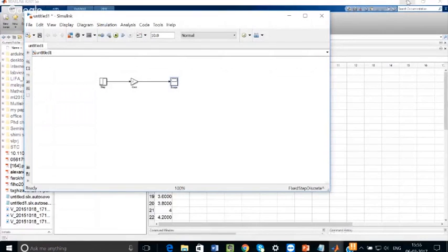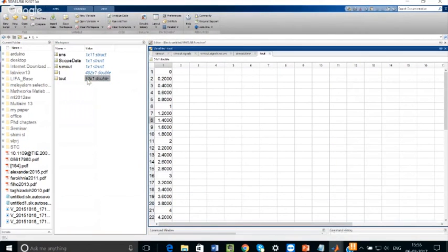So whenever you run a real-time system, when you connect hardware, you can never give it a variable step. You have to give it a fixed step. So here you can see the value, say 51. Now it has become 51. Earlier it was repeated, and here you can see it is there only one time. It is not repeated 3 times.